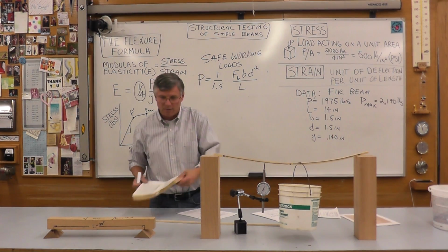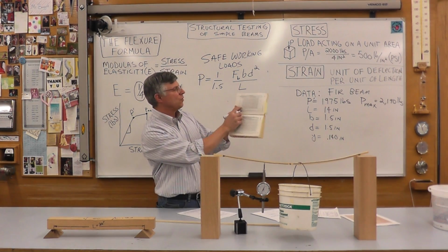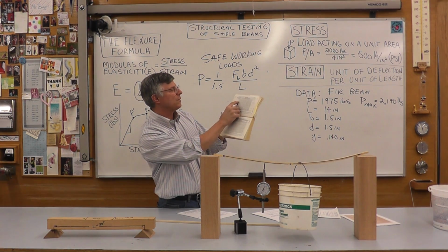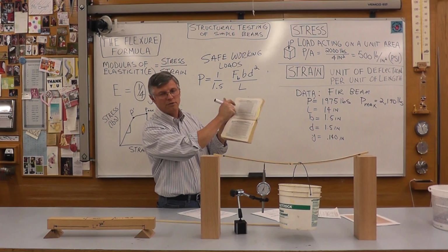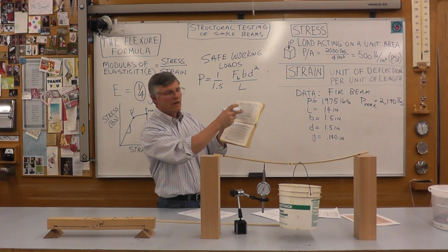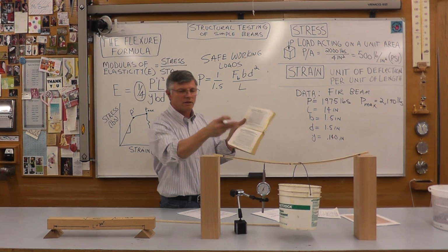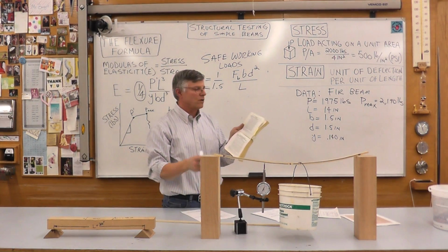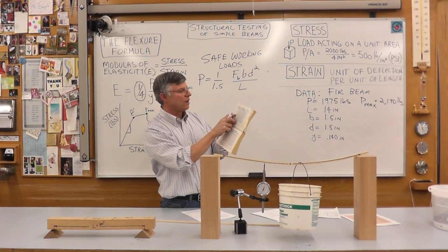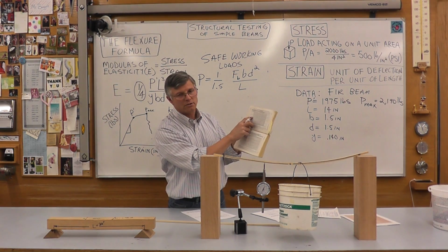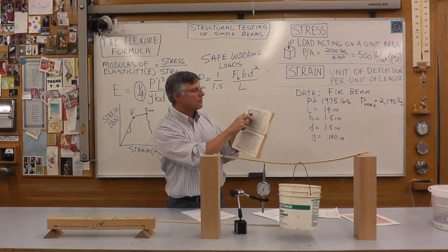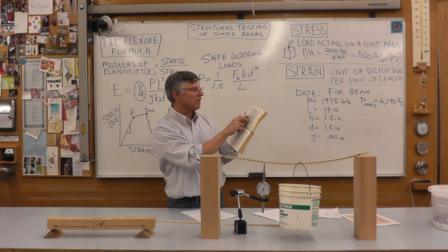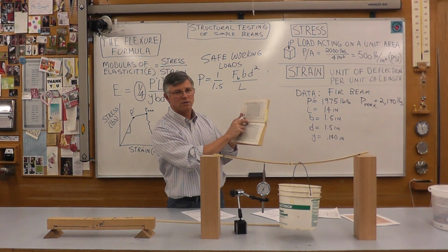In the Uniform Building Code, you can look this up online and other places, but the FB is going to be in your floor joist span tables. So you can say, I've got a 2x6 that's spanning 10 feet or 20 feet or whatever, and it's 16 inches on center, so below the span information is going to tell you what the FB value is, and then there's notes at the bottom of these tables.